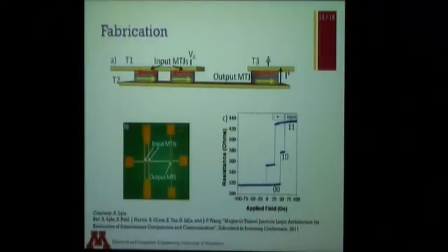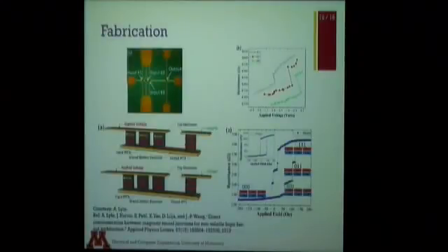They also did something very interesting with this. They also fabricated 3 input MTJs. Now, again, that looked exactly like the 2 input MTJs. There were now 4 pillars of MTJ stacks on this one shared bottom electrode, and then that was the graph that they got out of it. But what this allowed them to do, in addition to the NAND, NOR, OR and NOT operations, was the majority logic gate operation. And the majority logic gate operation is also a universal operation, just like NAND is, NOR is, and the set AND or NOT is.